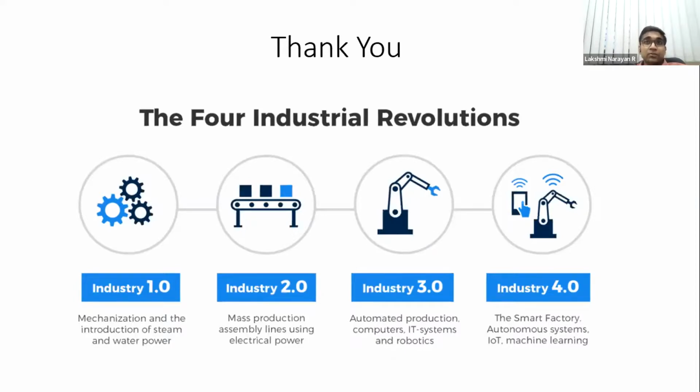Keyhole porosity is not such a big deal. Okay. So from the structural integrity point of view, I look at keyhole as a problem, and it leads to greater porosity. See, the other way, if you look at the other melt pool shape that I showed, right? If you look at a wider melt pool, that also ensures homogeneous melting. So you can retain the energy in a wider melt pool, and the aspect ratio can be lower. So you can achieve both these things. Of course, a little bit of dimensional accuracy goes away with that. I agree, but you can achieve both these things. You can ensure no porosity as well as homogeneous melting with that strategy.